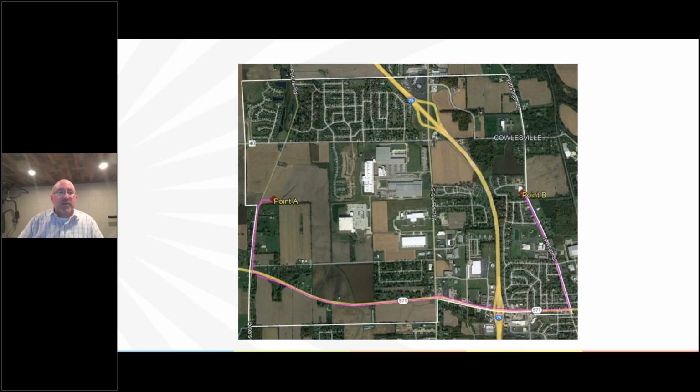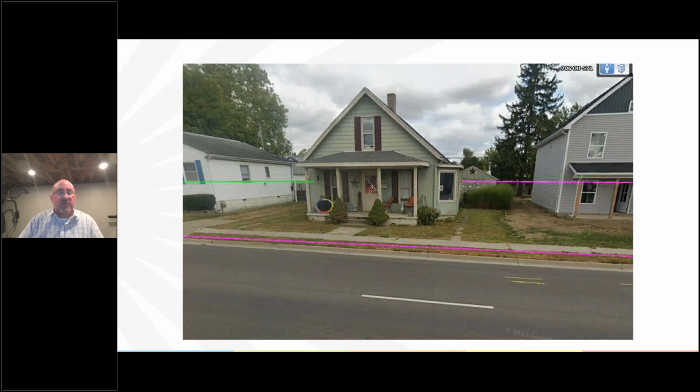So we eliminated the south route, the pink route down at the bottom, due to limited pole placement between building, sidewalk, and curb. Here's a street shot view. You can see how close the houses are. You can see there is not much room between the sidewalk and the curb. Putting in a 69 kV pole in there probably would have disturbed the sidewalks and would have required a lot of infrastructure changes.